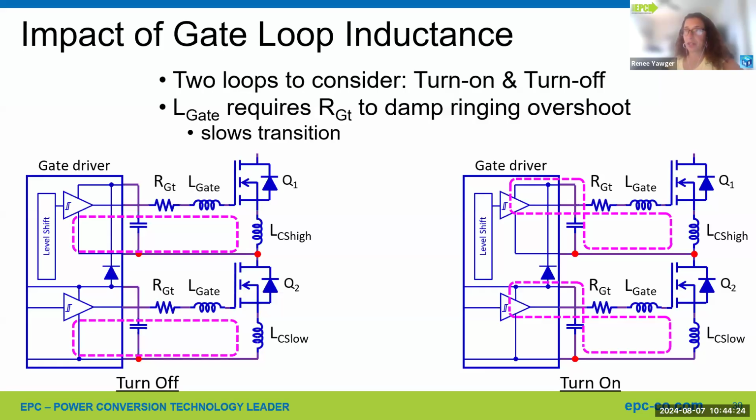You mentioned no need to go to negative voltage to turn off. Then why do people worry about spikes that may turn on the FET? Hmm. Yeah, that's a very good question. First of all, yeah, that's true. Negative voltage, we never use it and we don't recommend it because it's more trouble than it's worth. And a negative voltage actually increases the voltage drop of the return path, the diode function. So the question is, well, if you don't have that, there's not much margin between, say, ground and the threshold.